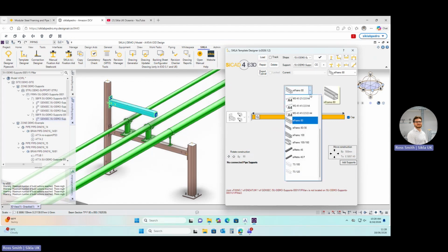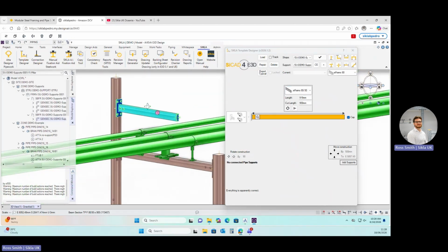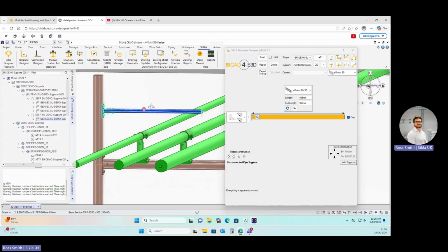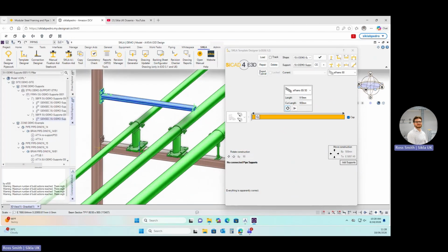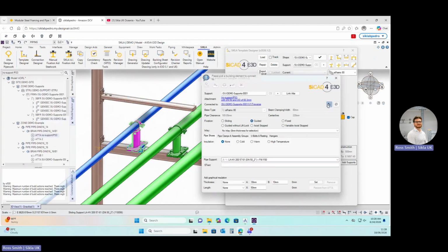Now you can see that I can reduce down to 8030 because there is a compatible component part. It would probably be more usable in the other orientation. So let's rotate that and say we wanted to connect a pipe shoe from here. Let's try and do that. Let's use the attachment designer. Let's click this part, okay, and link it to this crossbar.